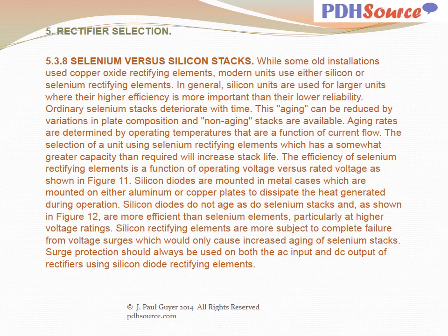With regard to the decision of selenium versus silicon stacks, while some old installations used copper oxide rectifying elements, modern units use either silicon or selenium rectifying elements. In general, silicon units are used for larger units where their higher efficiency is more important than their lower reliability.